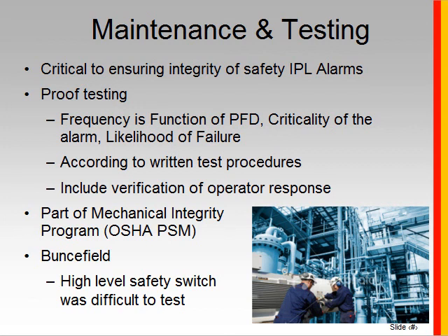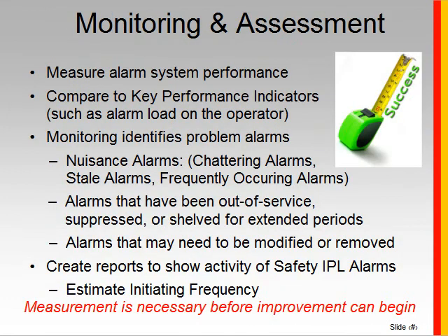And the only time it could be tested was if the tank was full and overflowing, essentially. So there was really no good method of testing that in situ alarm, which meant we couldn't verify or audit its performance.